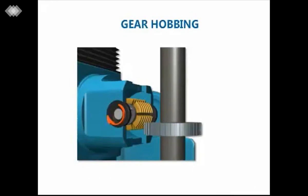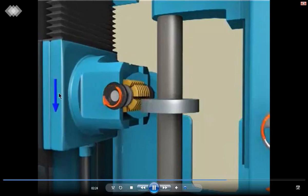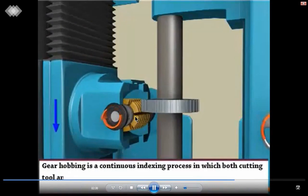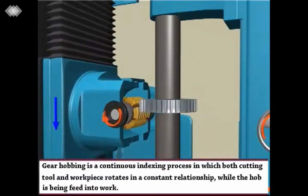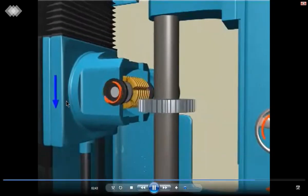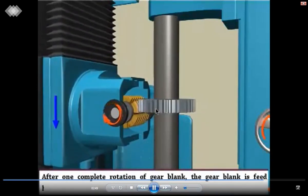The next type of gear manufacturing is gear hobbing, in which here we can see there is a gear blank, or the workpiece, attached to this arbor. It is engaged with this hob having multiple cutters, which is fixed on the reciprocating head. The hob is rotating, and the multiple cutters are engaged with this gear blank. They will cut the required depth on this gear blank by using this vertical up and down reciprocating motion, along with rotation while engaged with this gear blank.